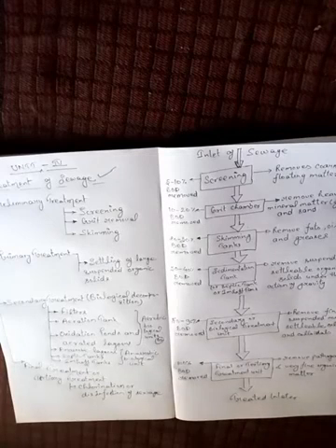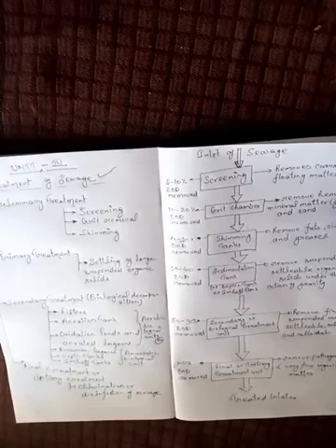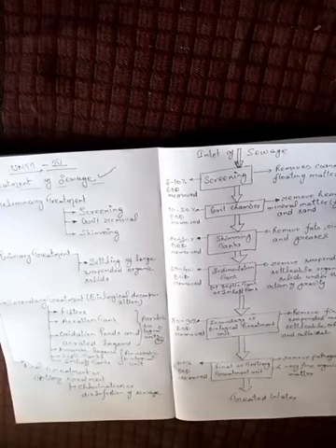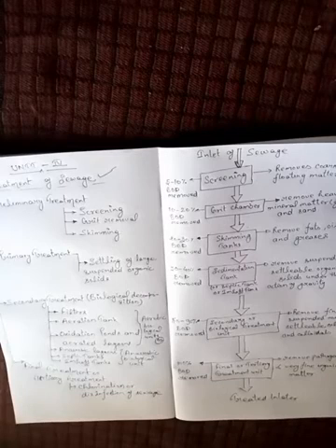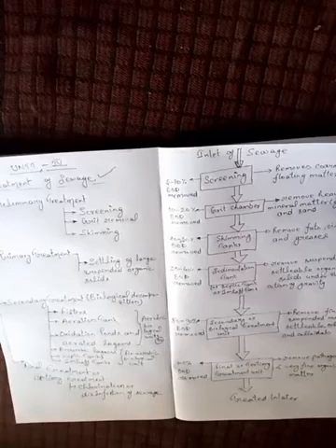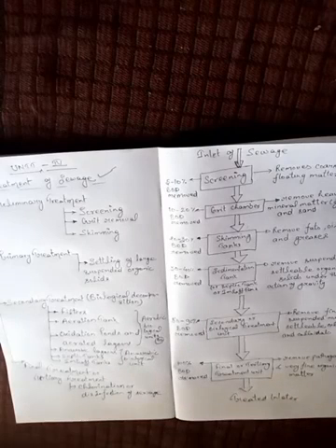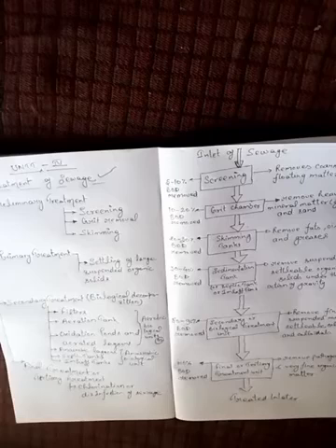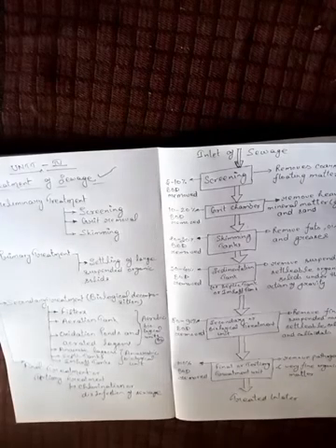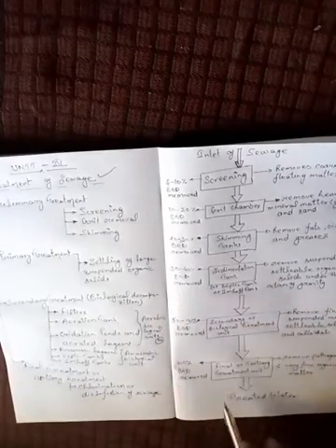Sewage is stored in rectangular or various types of structures or tanks in which the velocity of the flow is reduced to 0.3 to 1.2 meters per second, by which the suspended particles settle down to the base of the tank under the action of gravity. In this step, 30 to 40% of the BOD is removed.